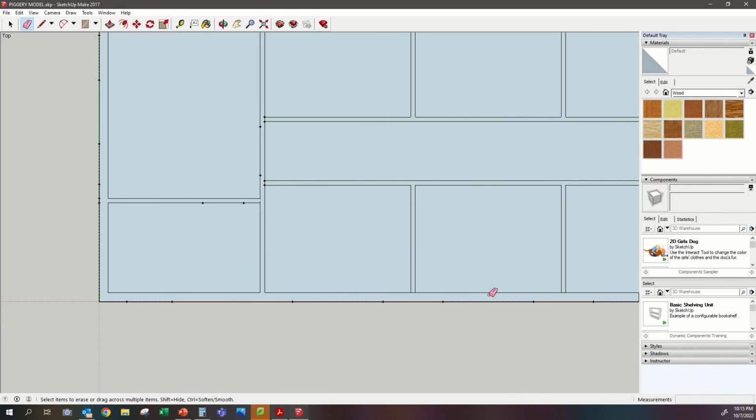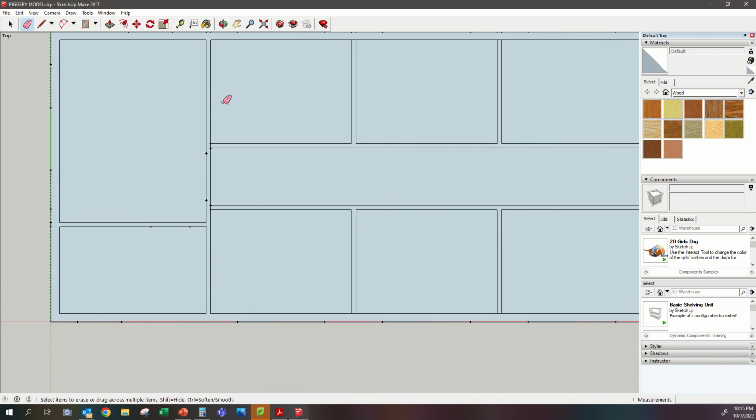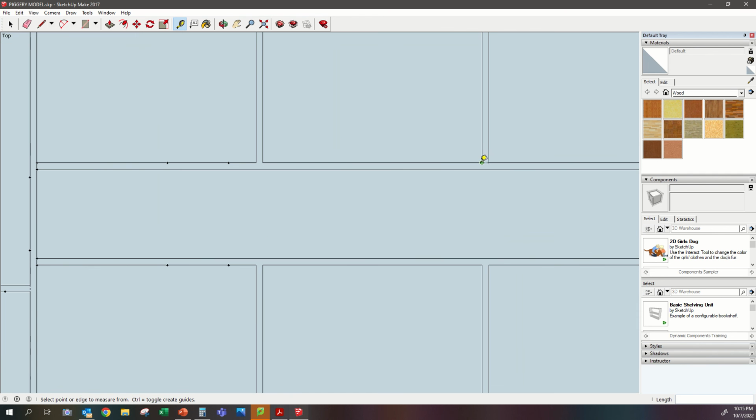We can hide all this geometry later, but we're going to keep it right now as we develop the rest of this. Okay, so as we move on to the inside here, I'm just going to decide on a measurement from the inside corner here of, let's do 400. Okay, 400 from the inside, and then we'll make this pen gate 900 wide. Okay, so 400 from the inside, 4,400. And we'll make it 900 wide again. So from the inside, we're going to go 400, enter, 900, enter.